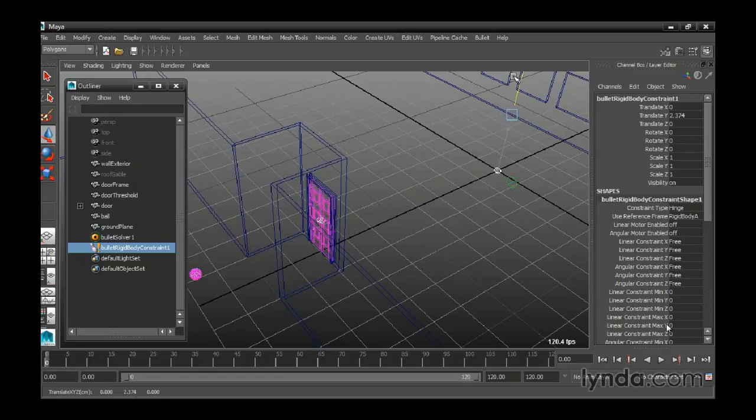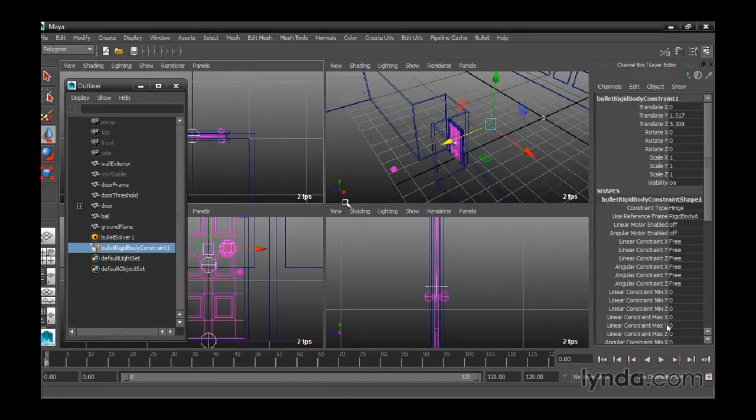The constraint actually moves to the side. And if I move it forward, we will see that it doesn't really track with the transform manipulator, or the Move tool. Don't panic, this is just a minor display glitch. If you simply rewind in the timeline, that will refresh the simulation and the constraint will snap to the position of the Move tool.